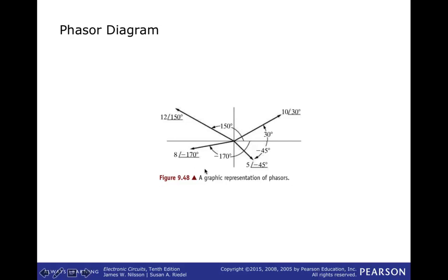So here are several phasors that are all illustrated in the phasor diagram. You can see you're illustrating the magnitude and the phase angle. This is sometimes useful for visualizing whether things are ahead in phase or lagging in phase, and sometimes useful also for visualizing things like three-phase.